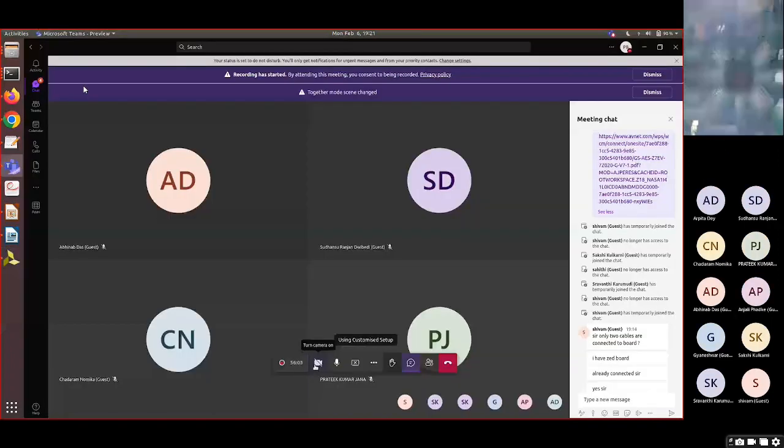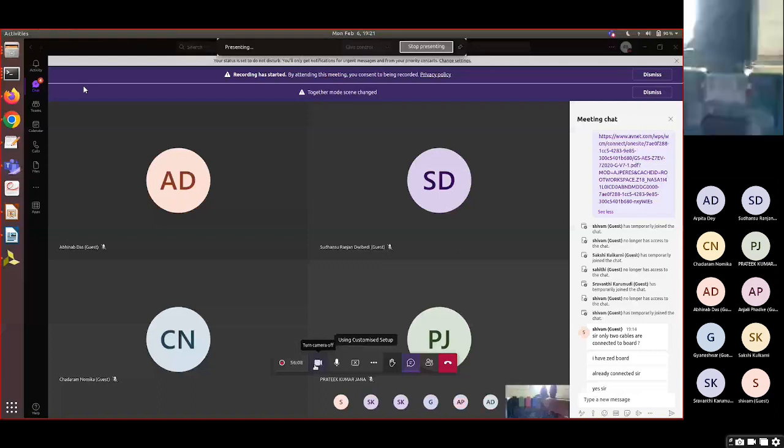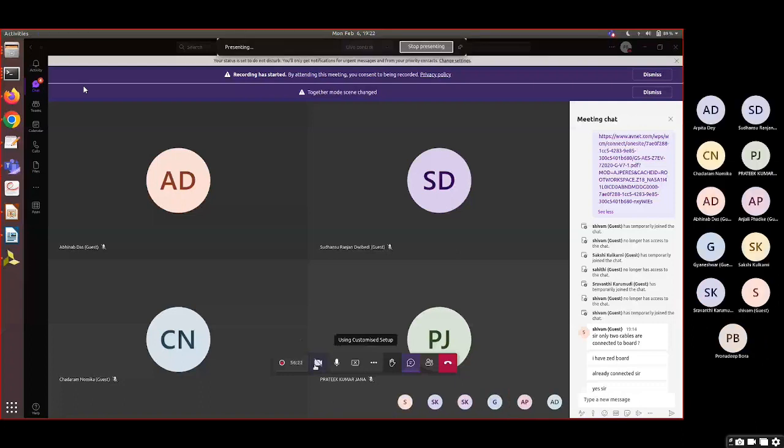You can see here, this is the JTAG pin. This is the program option, correct? That pin only you need to connect to program the PL side of the Zynq board FPGA, right? So only this thing is required, and we have to switch on the device.